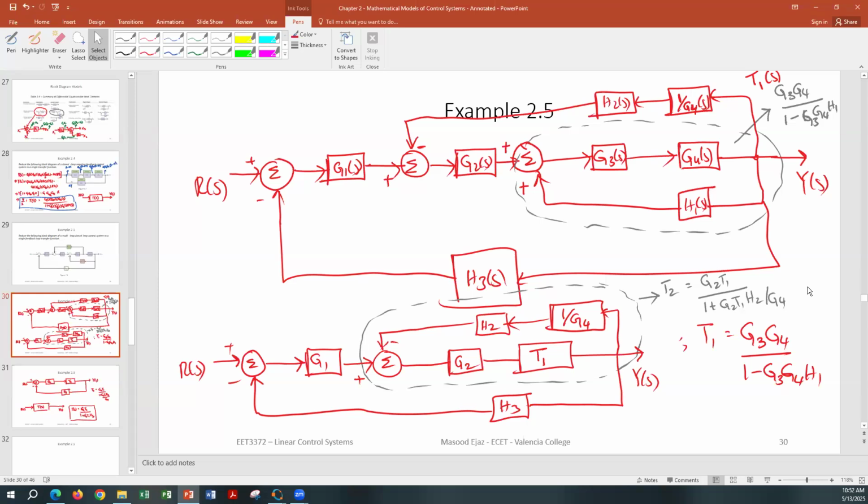Yeah, go ahead. So you have two feed forward loops. You cannot eliminate that. You'll have to take the signal from the straight loop, and then you have to jump from the other loop. We're going to discuss that under the signal flow graphs. But remember, feed forward, and that's a good question, because I have seen that mistake as well. If you have two feed forward loops, make sure you do not eliminate the feed forward loop using the feedback loop formula. That is not applied on feed forward loop.